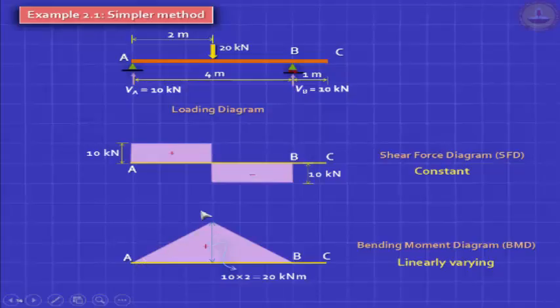And there's a relationship which we'll prove later, that the shear force is given by the derivative of the bending moment. So you have a line with a constant slope, the positive slope, and that is your shear force. You have a linearly varying bending moment, but with a negative slope. So there is a link, and not only that, where the shear force is changing sign, passing through 0, you're hitting the peak in the bending moment.